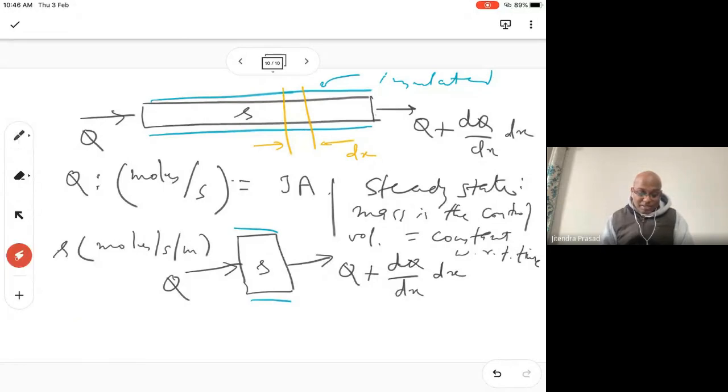So that really means we can work out the equation here. This Q is coming into this control volume system. So we have Q coming in, so we write Q plus, and because of the source the mass is also entering the system, so S, which will be a function of x, so Sx multiplied by dx. Yeah, dx, because this is per unit length.